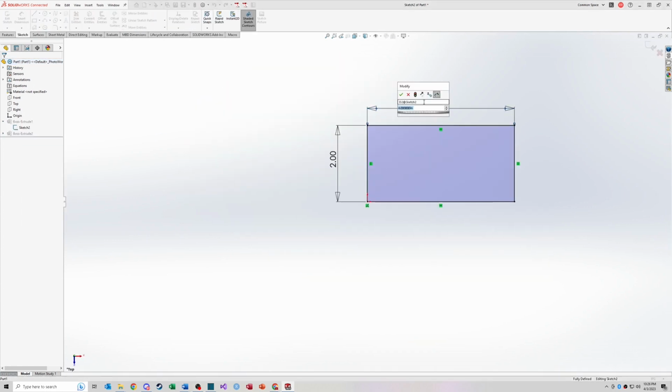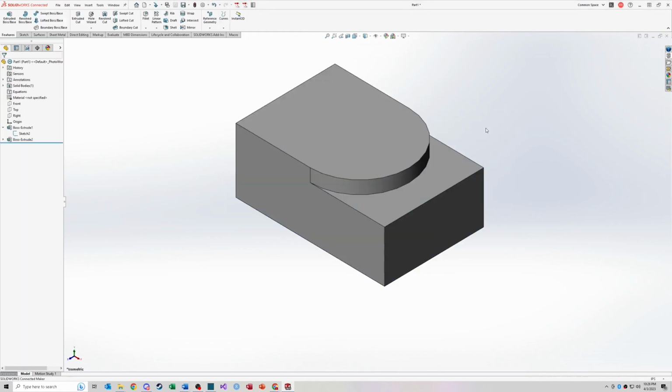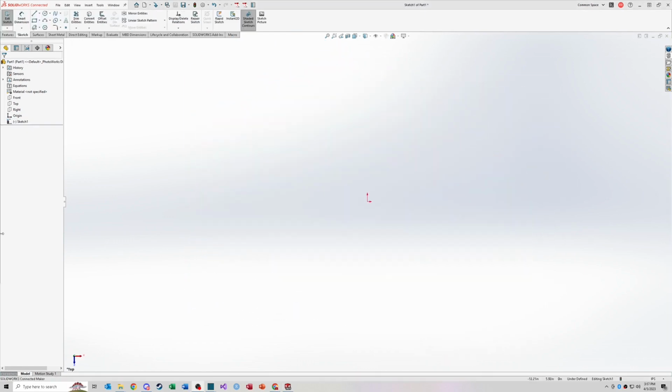And the nice thing about this, just like a lot of other things in SolidWorks, is if I go in here and I change this to a 3-inch width, I'm going to go normal to, I'm going to complete the sketch. You can see that that circle is still centered and it's still using that model geometry from the convert entities command to keep that outside profile.